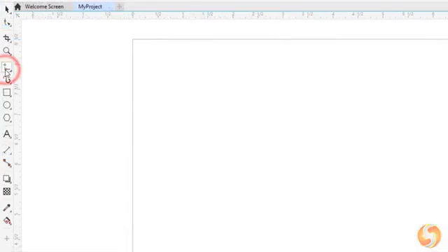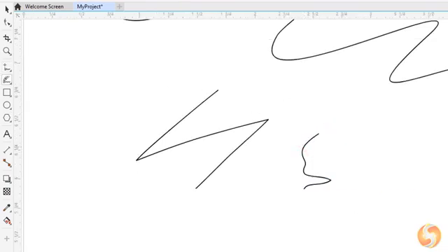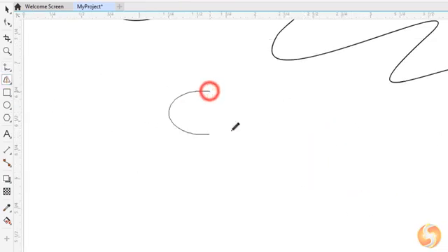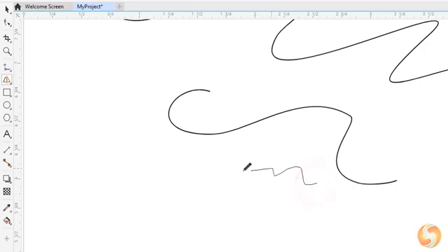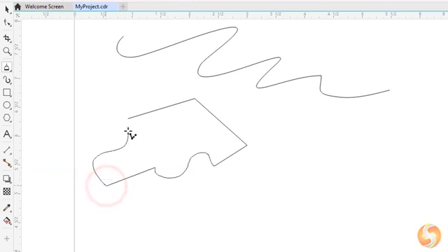Enable the Freehand tool to draw freehand by clicking and dragging on the document. You can also try Live Sketch and Smart Drawing to have your strokes and shapes smoothed and adjusted automatically. With the Polyline tool, click several times to drop straight segments and click and hold to draw freehand as you like. Segments and curves follow one after another until you double-click or close the shape.